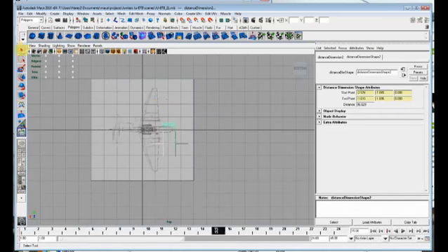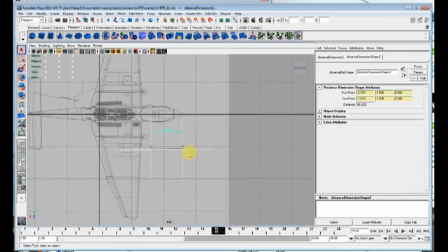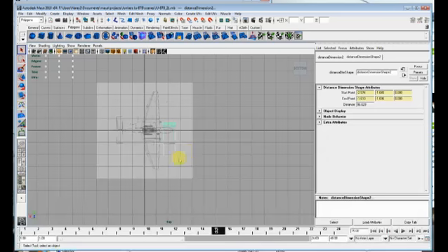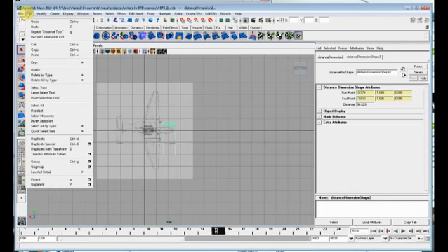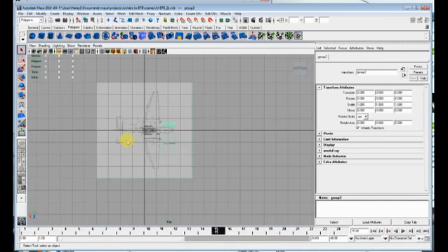So what you do is you go out, you hit the Q key, that's your quick key, and you select everything. And once everything is selected, that means everything turns white except for the last object, which remains there. And you go up to Edit, and you go all the way down here to Group, Control G. And when that groups everything, it recenters everything at the origin of the world, at the 0, 0, 0 point.